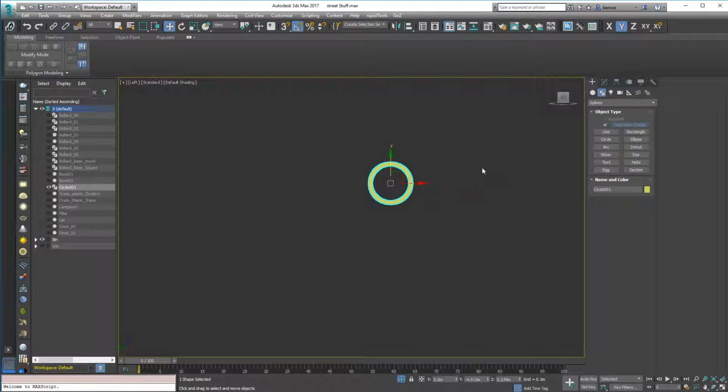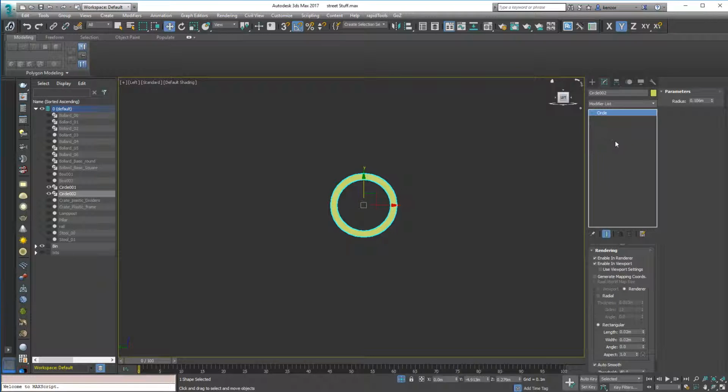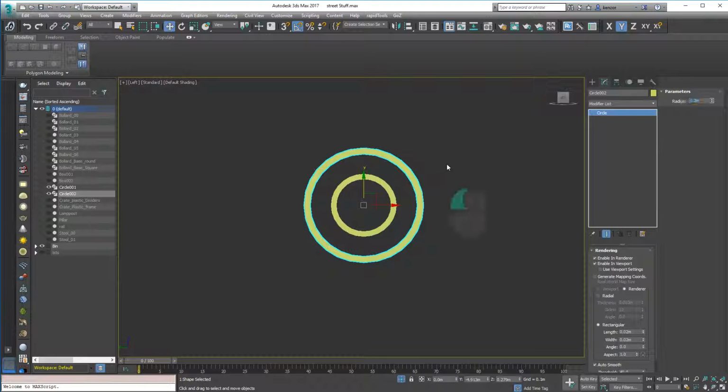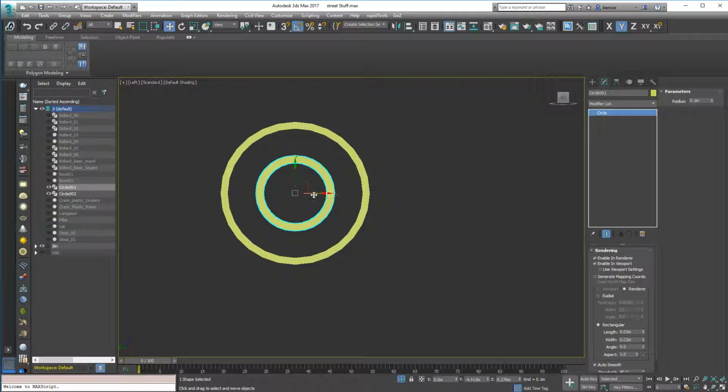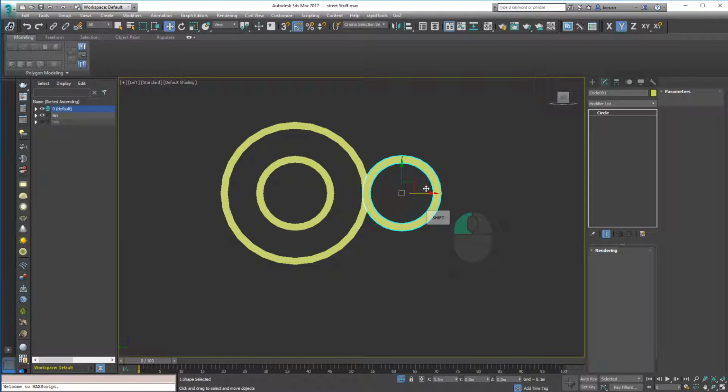So let's have that guy, and if I Control V, I can make a copy of it, and we're going to make it 0.2 meters wide. Just check that radius is exactly 0.1. Because we've got this very regular design, I'm going to be careful about my measurements. So I want this guy to be perfectly over here, which I think is 0.3 meters.